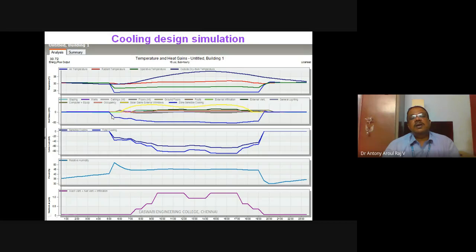So this is a type of control. It is possible only in proportional controllers. If you are going for on-off controllers, it is very difficult to have a control like this. An on-off controller may not go like this. Okay, so it will rise and fall, rise and fall. So that is how it will go. Here also those variation spikes will be there in the temperature. Here it is assumed that pro rata, or proportional to the load, we are supplying the cold. For example, you think there is an AHU with a proportional controller. So that will be supplying like this.